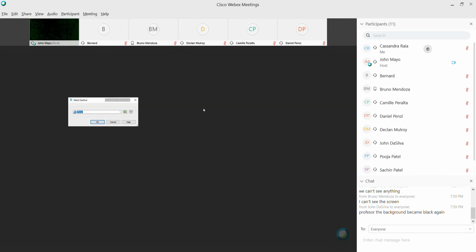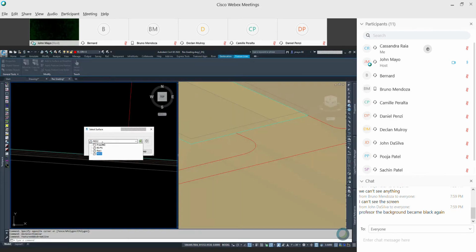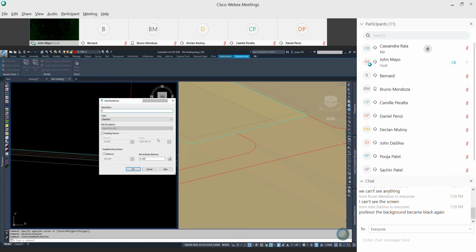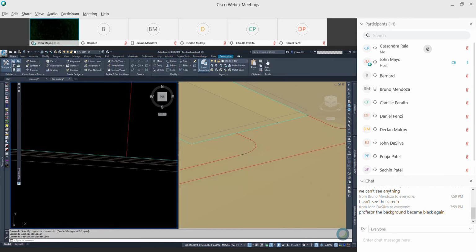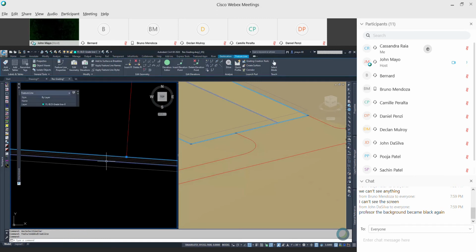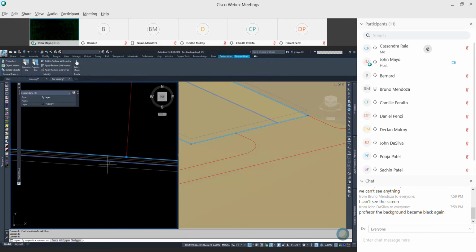This is again, I know your screen went blank, my Res 2 surface, hit OK. And again, I have curves on my driveway. I want to keep that mid-ordinate distance low. Right, now you see how the surface is forming around there. And now I'm just going to raise my whole building up. And this is where you want to raise all 3 of these together, right?